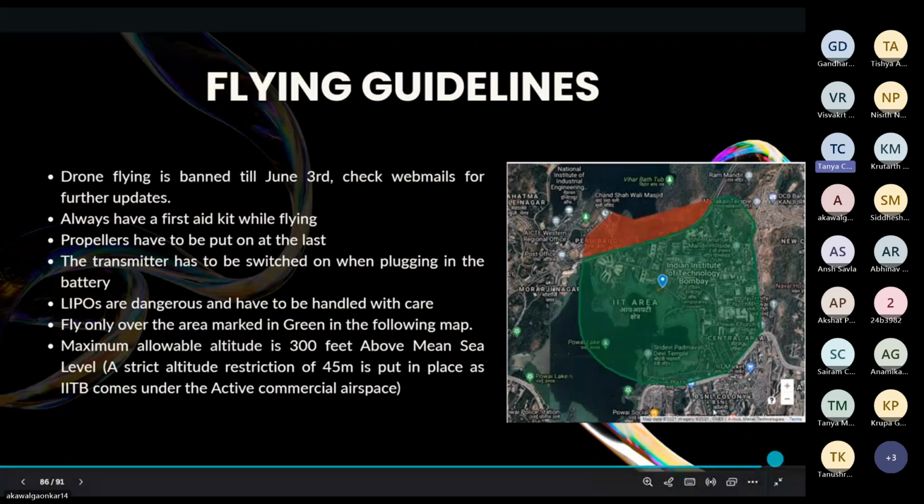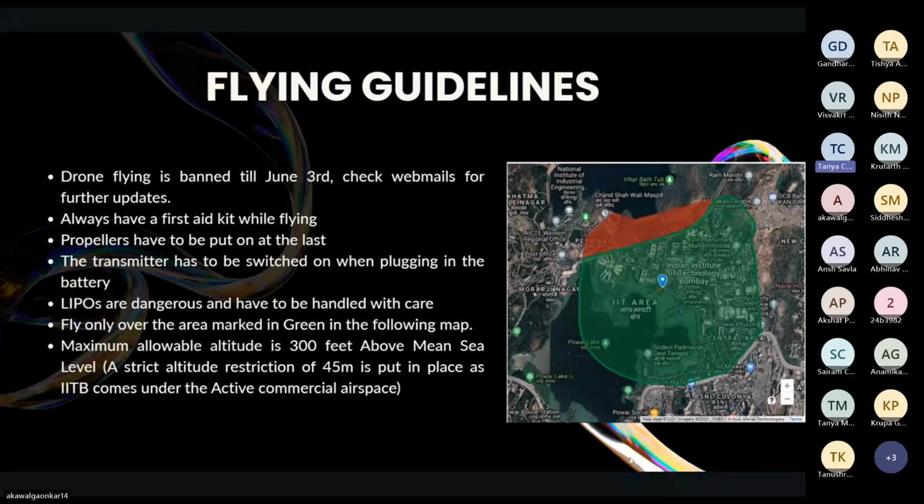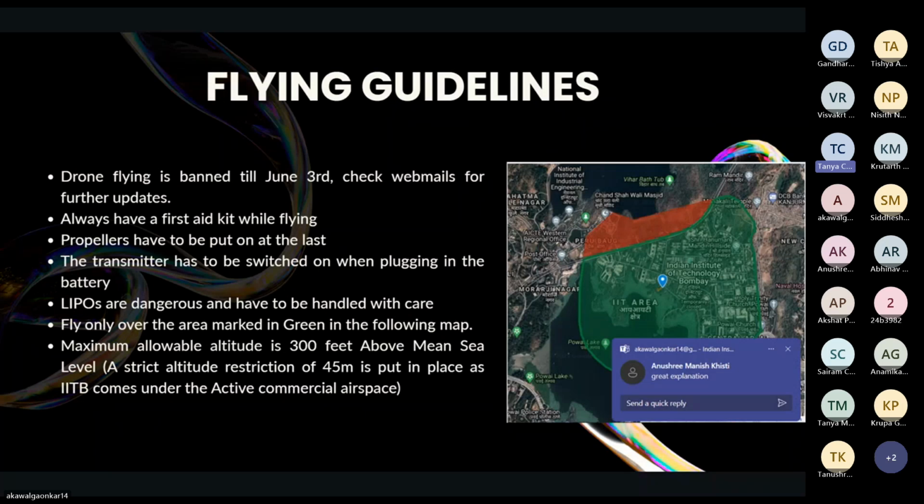Before we end, a quick note on drone flying inside INSTI. Drone flying is banned till 3rd June. Check webmail for further updates. Always have a first aid kit while flying. Propellers have to be put on at the last. The transmitter has to be switched on when plugging in the battery. Lipos are dangerous and have to be handled with care.